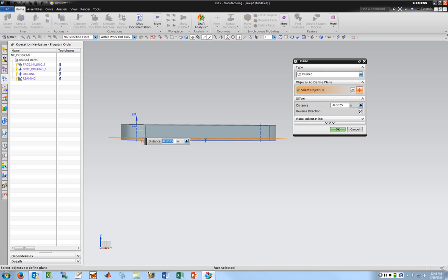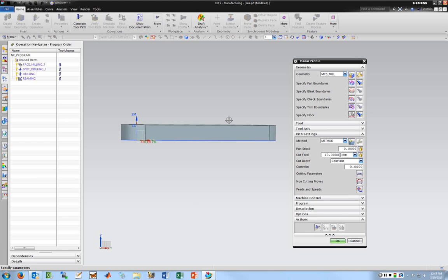So if I want to cut deeper, let's just make it a positive sign. I can cut it deeper, and it mills it nice all the way around, but I'd have to have a little extra stock here for something to hold on to, and then I'm going to have to do a facing operation on this side. So a lot of which way depends on what you're machining and how you want to finish it. Since I'm going to do a finishing operation all the way around it, let's go ahead and just leave it on the long side and assume you've got some extra stock down here. So I want to machine past it. Let's go past it that 16th. Hit OK. And that's where it's going to machine down to.